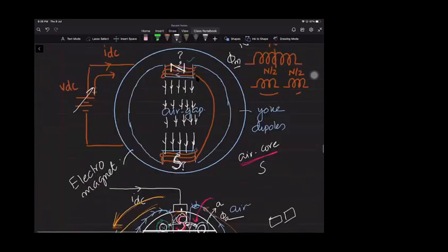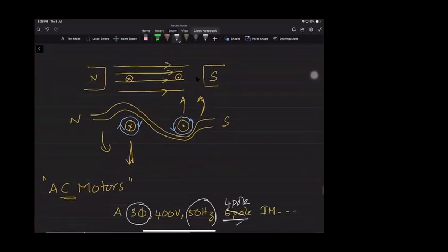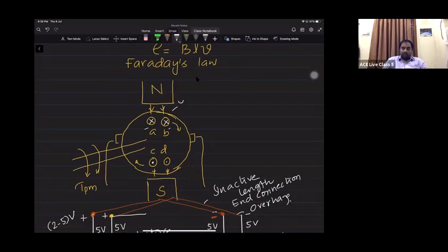Yes, sir. If you want to use this machine as a motor, then instead of driving the armature with a prime mover, if you pass currents into the conductors, the current carrying conductors will experience a force and it rotates. But we need EMF, so for that we have to move the conductors. The field is required there. So how is this field produced?